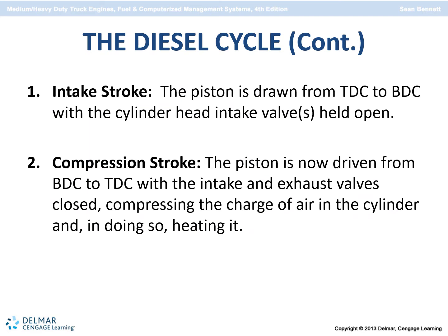Okay, so we have the intake stroke. The piston's moving down, the intake valve is open, and it's filling the cylinder with air. Compression stroke, both valves are closed. The piston's traveling from bottom dead center to top dead center with the intake and exhaust valves closed, compressing the air charge in the cylinder and heating it.